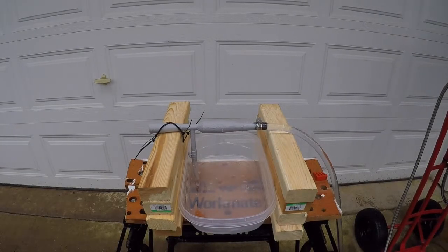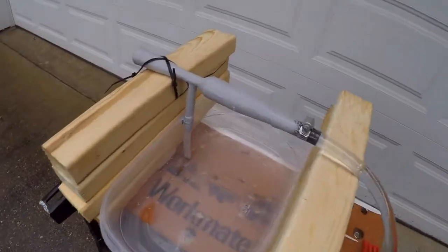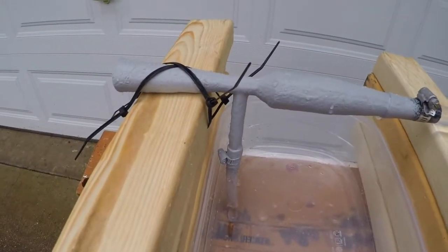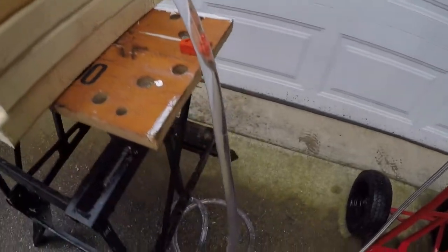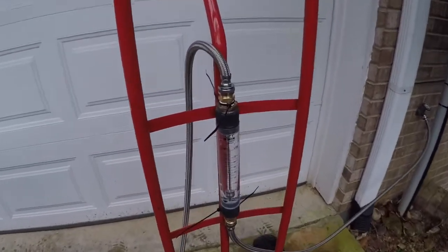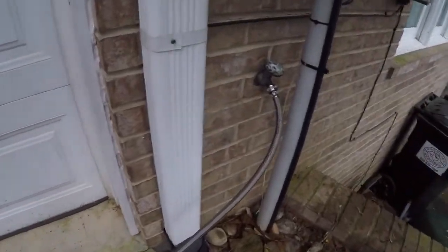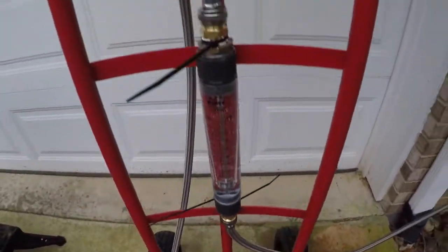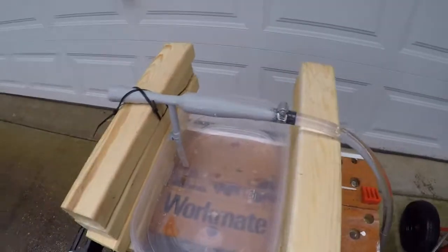So now we've got our experimental setup here that we'll show you. Essentially, as you can see here in this video, we have our Venturi mounted on some 2x4s, and that's our edited Venturi that you see there after we've made some modifications to it, as we'll discuss here in just a second. But basically it's hooked up over our bucket of suction or mixing fluid that's being sucked up through the Venturi and mixed. And how it works basically is we have our hose connected to a water spigot on the exterior of a home, and that flows to a flow meter that's oriented vertically, as you can see, and then it flows through another hose that goes up to our Venturi.